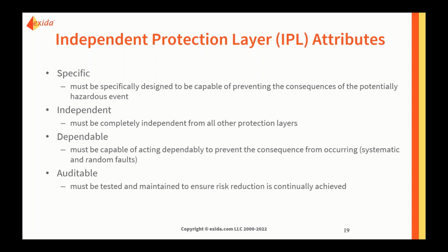And here we have the 4 standard criteria. Specific, it's got to work. Independent, it must function independently of all other protection layers, because the math that we use to calculate our accident frequency is probability multiplication. And in order for that math to be correct, each protection layer must be fully independent and not correlated with the behavior of each other protection layer. And again, that's the one that is the real core of the LOPA technique, confirming that we've got independence of